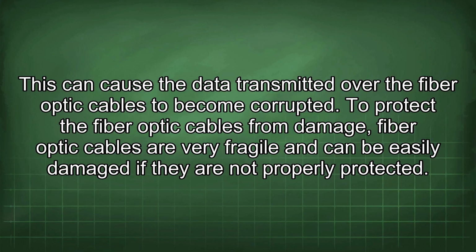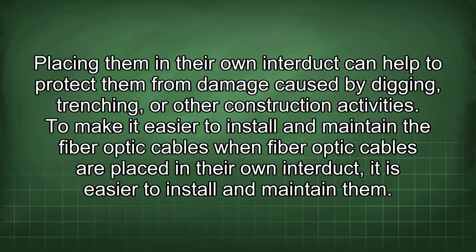To protect the fiber optic cables from damage: fiber optic cables are very fragile and can be easily damaged if they are not properly protected. Placing them in their own interduct can help to protect them from damage caused by digging, trenching, or other construction activities.